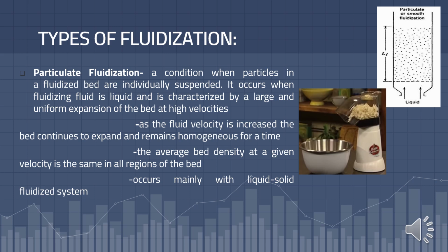An example would be a hot air popcorn popper. The popcorn kernels, all being fairly uniform in size and shape, are suspended in the hot air rising from the bottom chamber. Because of this intense mixing of the particles, akin to that of a boiling liquid, this allows for a uniform temperature of the kernels throughout the chamber, minimizing the amount of burnt popcorn. After popping, the now larger popcorn particles encounter increased aerodynamic drag, which pushes them out of the chamber and into the bowl.